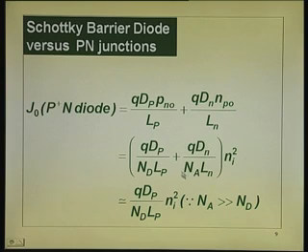But when we talk of a P plus N diode, acceptor doping concentration is large compared to the donor doping concentration. So, this term in the denominator is very large compared to the doping Nd. So, this term actually goes off, very small, 4 or 5 orders of magnitude larger in the denominator. That means this term will be 4 or 5 orders of magnitude smaller compared to that. So, we could put that approximately as q Dp pn0 over Lp.